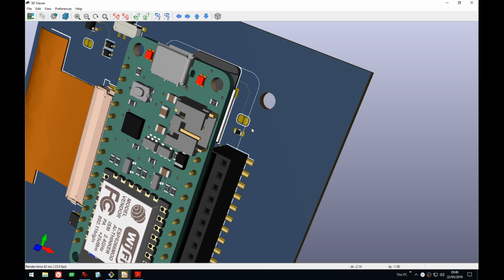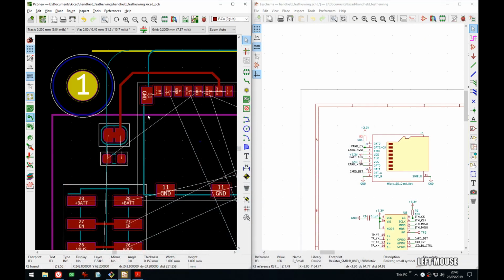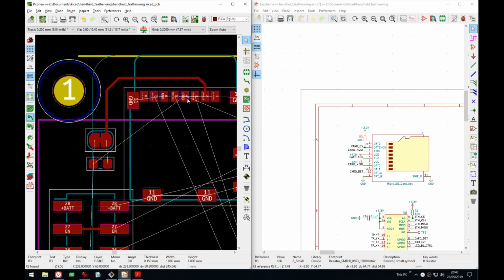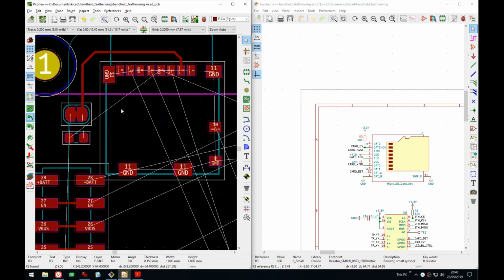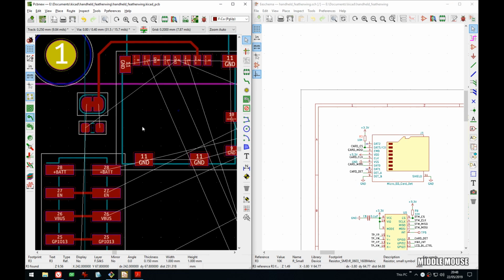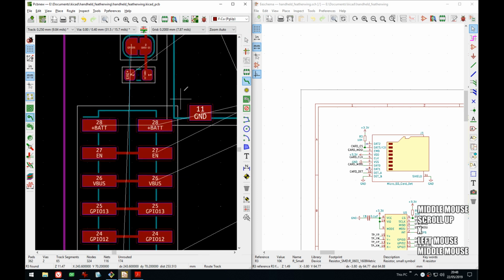Highlight mode, I mean, you saw how it works. It's not super great. Usually it's not so bad because it will only highlight the traces. But apparently a circle is just a lot of short traces. At least that's how the collision looked. But normally you would only see the paths highlighted and so on. So it's a bit better. But walk around or shove is sometimes useful as well.